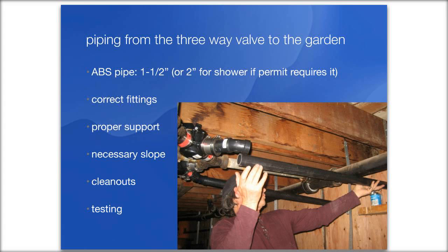Laura, do you have anything else to say about that? Yeah, just to add that on the Greywater, when you're diverting water to a Greywater system, there are no sewer gases in that system. So the main function of the trap and vent is to protect the home from sewer gas. So you don't have to consider that.